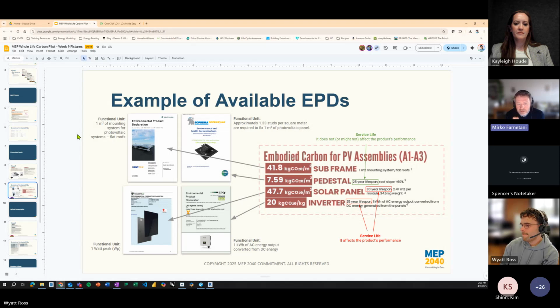Okay, so fenced in pink, you can see the outcome of the calculation we carried out. And particularly, all of this calculation obviously refers to the EPDs we have used in this assessment on the left-hand side. I think perhaps what is important to say here is to always double check the functional unit of EPDs because they could differ from the results that we want to produce.